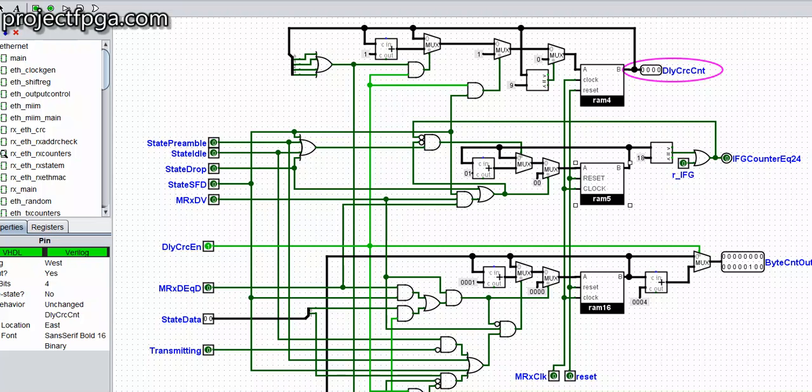And since we are receiving 4 bits at a time, 1 nibble per count, that is 4 times 8, which is 32, which is 4 bytes of data. So the delay CRC delays for 4 bytes count. It counts 8 times, allowing 4 bytes delay. Now we are going to see in a later tutorial what we use this delay CRC for, how we used it.